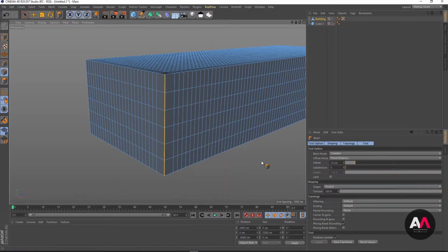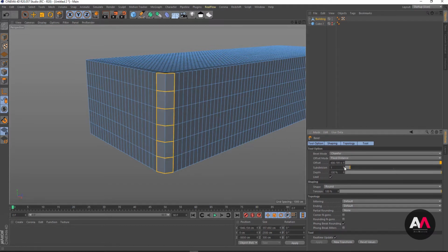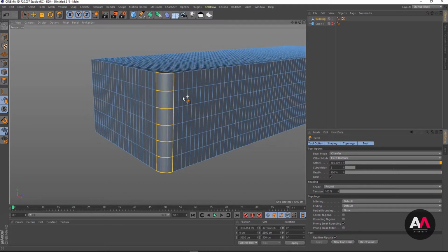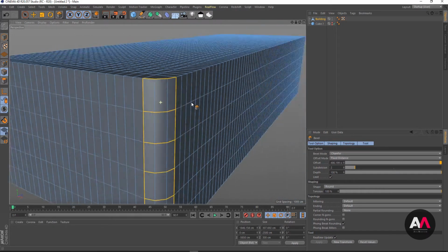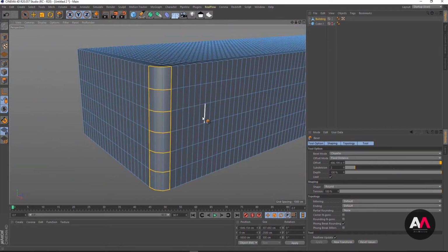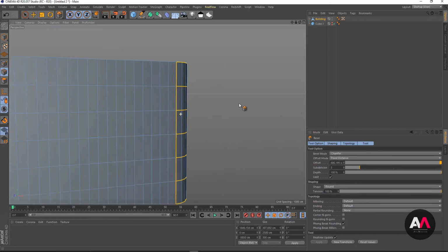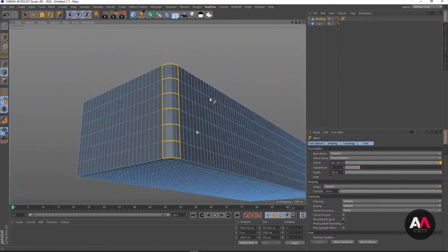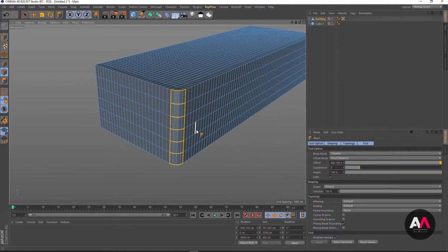You have it here, and check Limit on, and drag it to the maximum. Yeah, this is enough. And I'm adding subdivisions. The size of the subdivision must be almost the same as these two sides. I think maybe 3 should be good enough. Yes, it's okay. It's great.